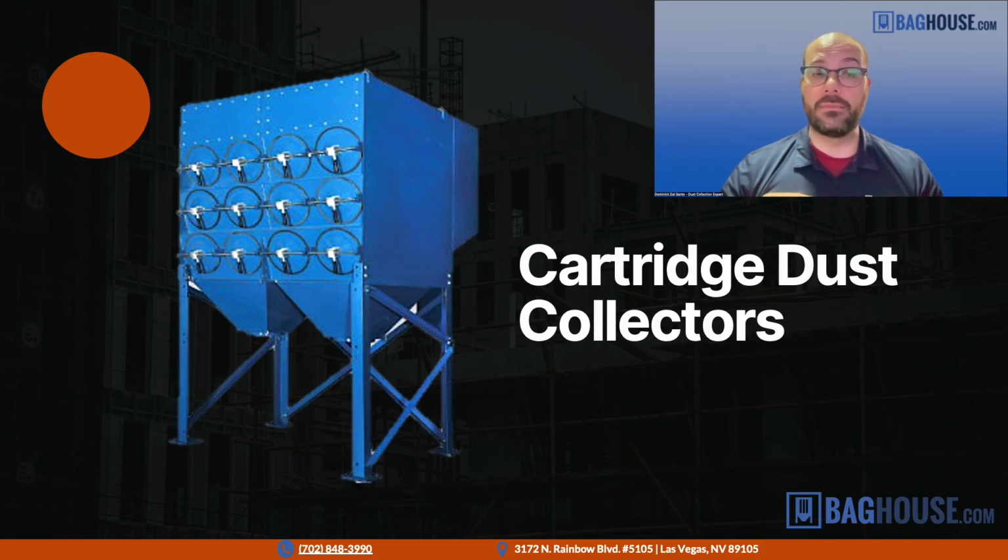Now, if we go back to thinking about the baghouse filters, we discussed the pleated filter elements here. So a common way to get the benefits of a cartridge collector in cement and mining is to take a baghouse and then use these pleated filter elements. These pleated filter elements are a type of cartridge that is designed to retrofit into a baghouse. So the media is pleated and jammed onto the filter, so it has more filter area than a bag, but it's not jammed so tightly like the cartridge collector cartridges, where you get a lot of the problems where the dust can't be removed and things like that.